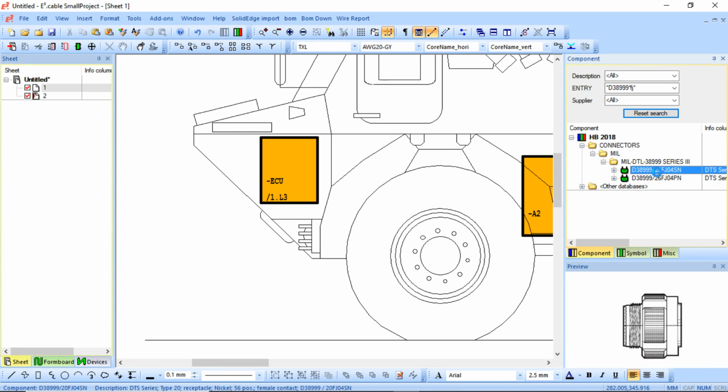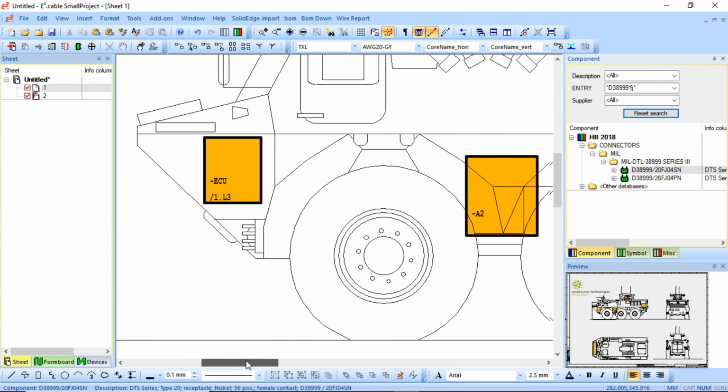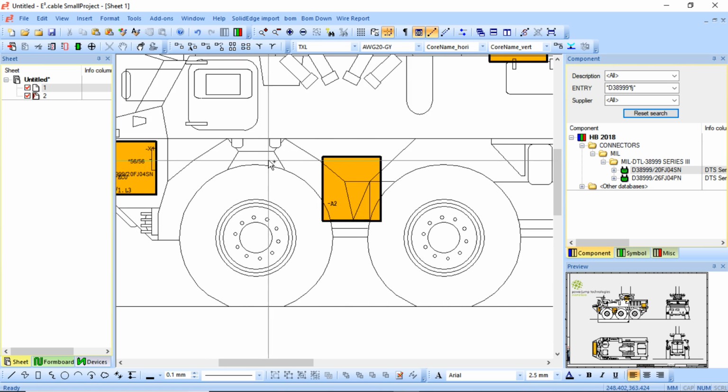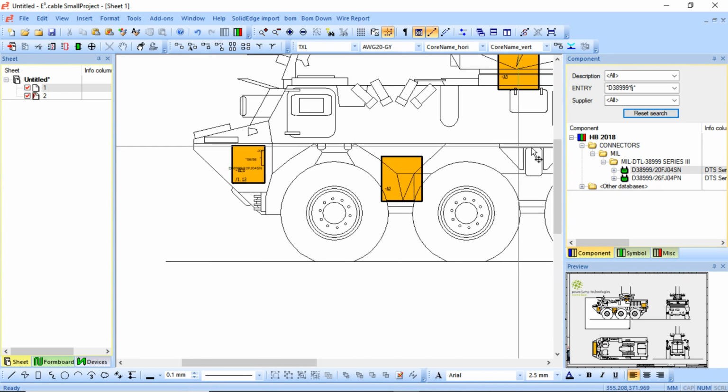And you can see here, if I click on one, it'll actually show me the image and what it actually is. So I can bring it over and place it directly into the block, and it'll actually give me a symbol to represent the 56 pin, the X1 connector, and that's the part number there as well. So these views can all be changed, but nonetheless, I can say I've got in these particular ones, I'll place just a few of them.